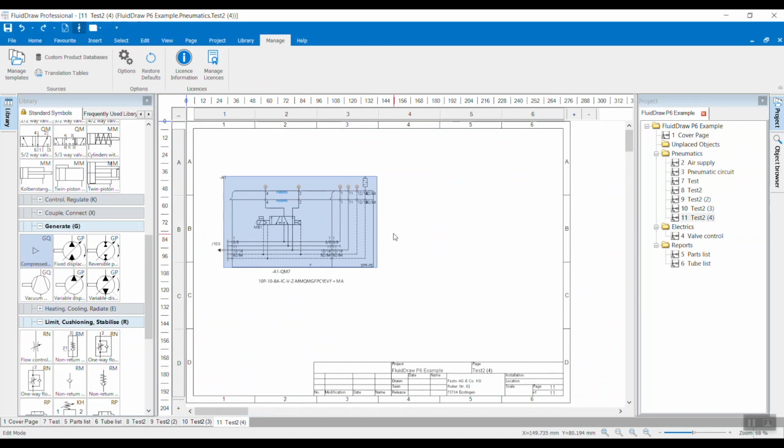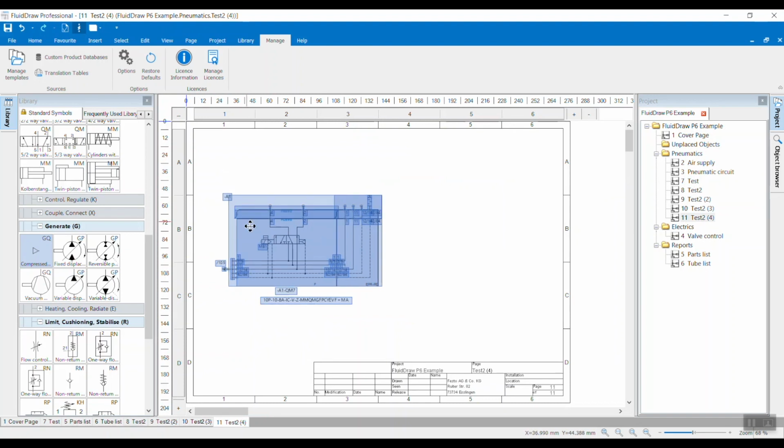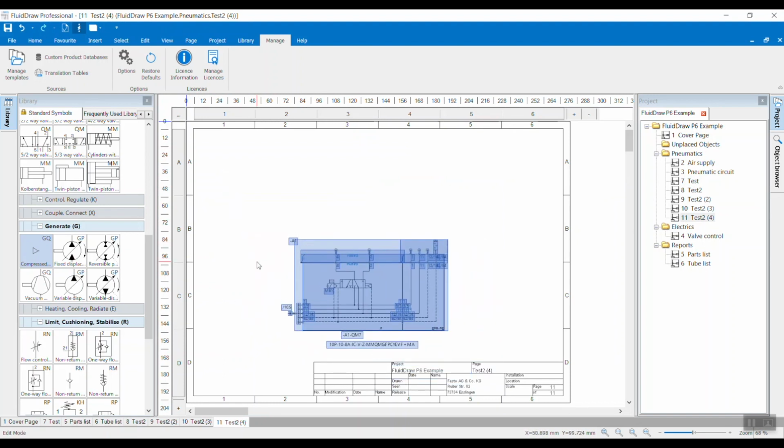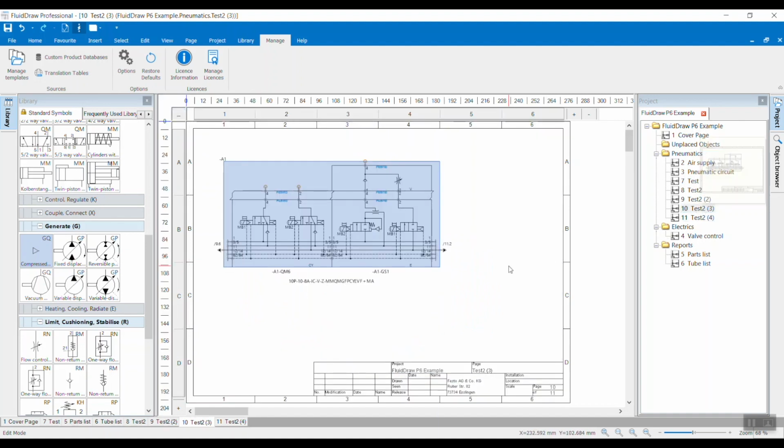So a quick tip on valve terminal placement. As you see here, our valve terminal is in the middle of nowhere because I didn't take particular care when placing the valve terminal. You can grab and move the valve terminal anywhere you want, so it's still freely available. But if you take a moment and anchor it properly in the first place, then the same anchor point is going to be used throughout each one and they won't have to get adjusted.